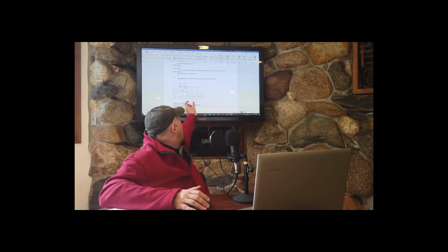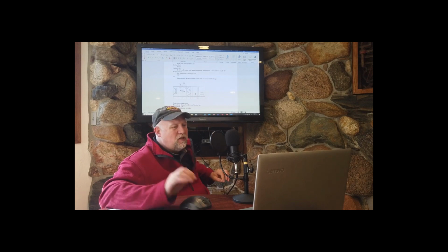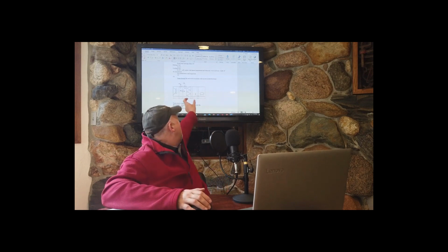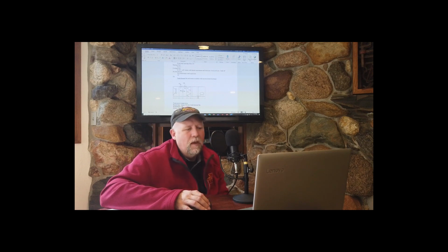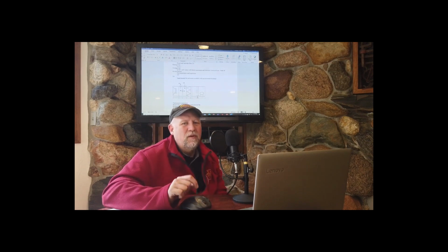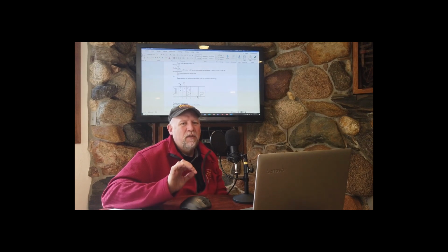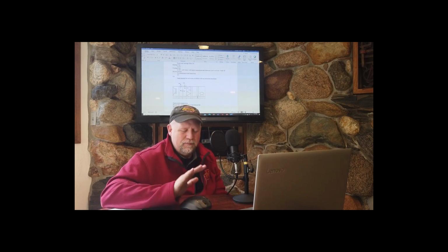So once again, back to the schematic. Here's the heating coil. Here's the cooling coil. Put those dimensions in that I just gave you. But notice there is a space in between those two. The space in between those two is an access section that you should leave in the air handler.